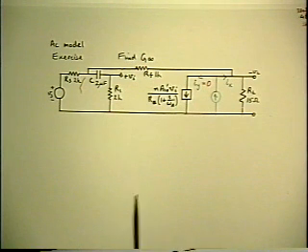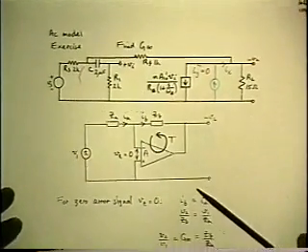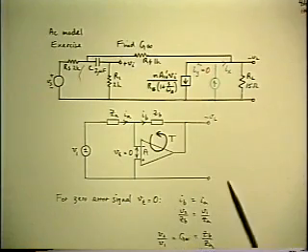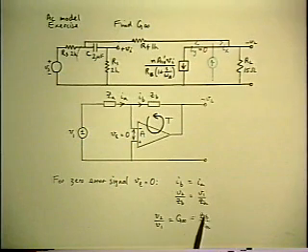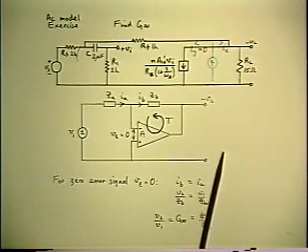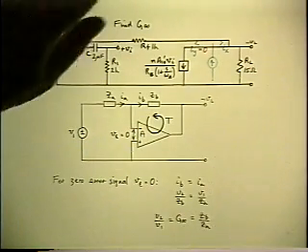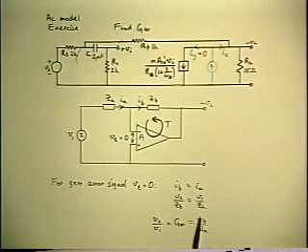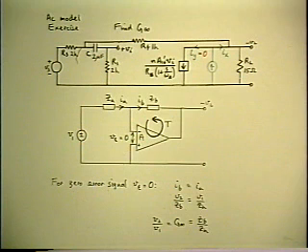The key to doing this in what looks like a different sort of circuit is simply to recognize that it's the identical problem to this one that we've already gone through. I talked about this already when I emphasized that the normal way that most people calculate the gain of this feedback system is to assume infinite loop gain, which is what allows you to say that the two inputs to the forward path are equal for zero error signal, and that's the condition you need to arrive at the result.